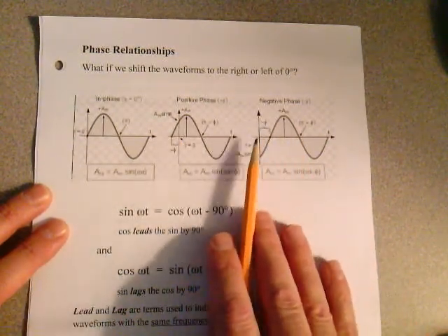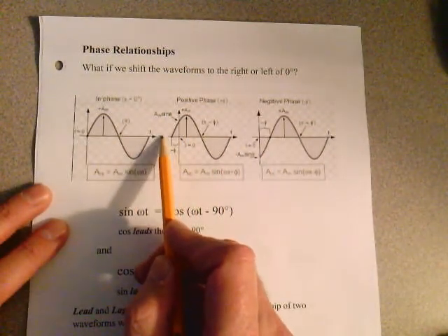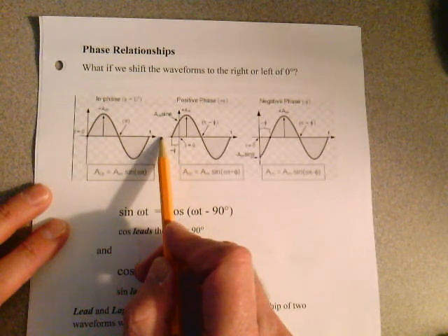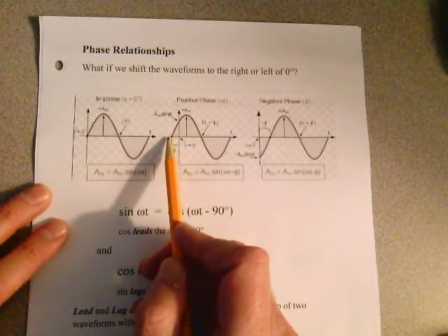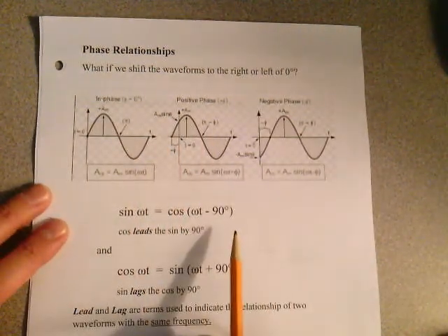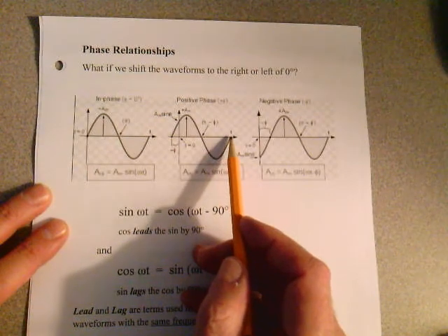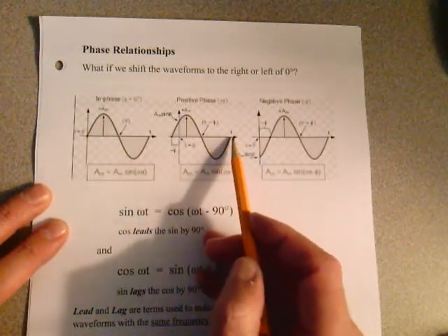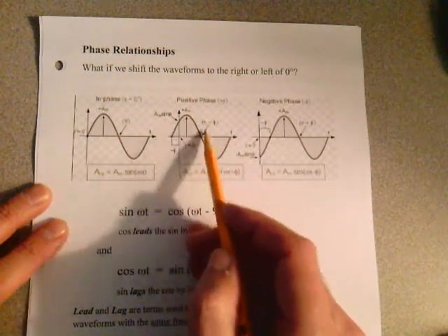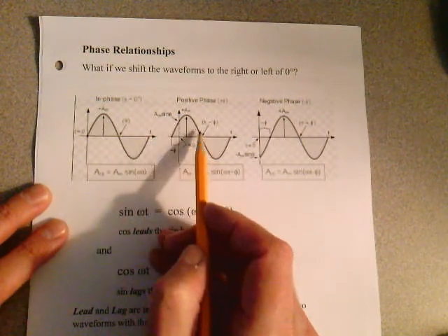The way you have to look at it is you have to be over here on this side, and you have to look at that waveform coming towards you. Remember that radius vector that rotated counterclockwise? Well, when you look at a sinusoidal waveform in the time domain, or in this radian domain on the abscissa axis, you have to be over here and look at it coming towards you.